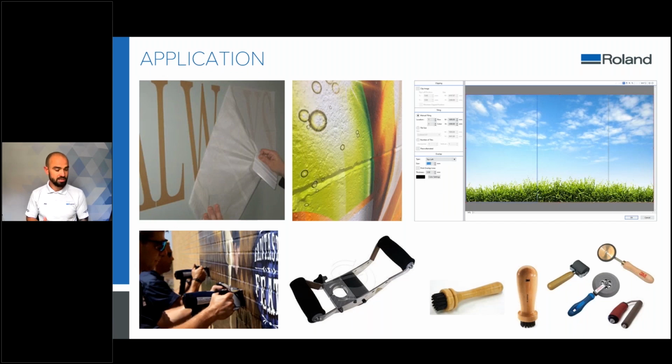And then there are those types of vinyls where you need to use a heat gun to go into the recesses and things. In terms of application, we've mentioned application tape. Those are for graphics that have lots of different elements cut out. And when it comes to the ones that need to go into contours and recesses, you need a roller or some kind of squeegee to get into those recesses. So you would use a heat gun to soften the vinyl to be able to go into those recesses.